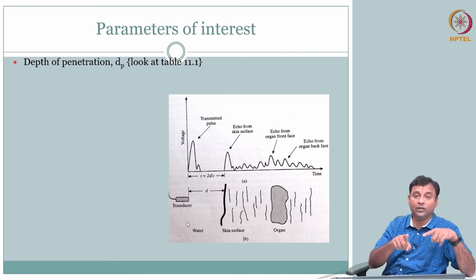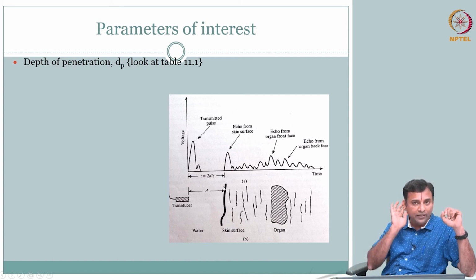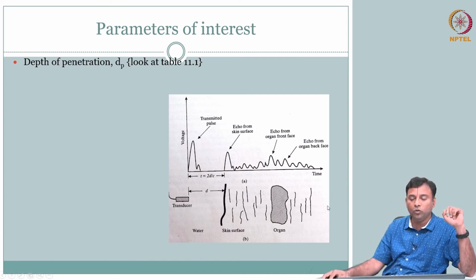The idea is we want to go to a different location and send and receive the echo. How soon can I go to the next location? How long should I wait in the same location? This is a critical question that we call depth of penetration, meaning how long you wait is going to be determined by how deep you want to get the echo from.